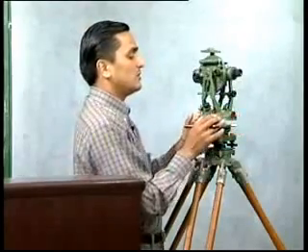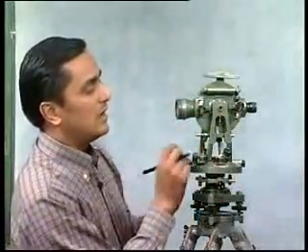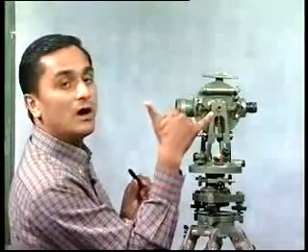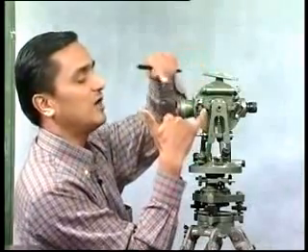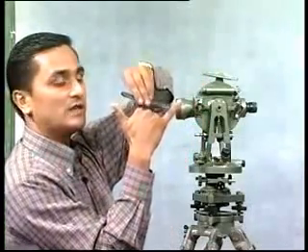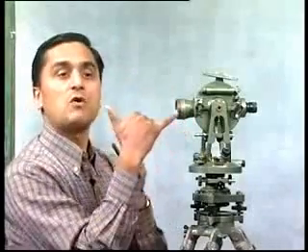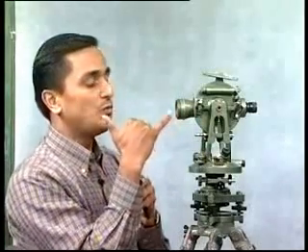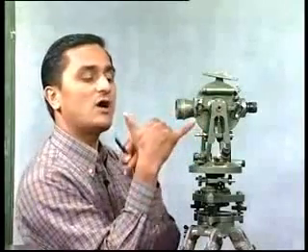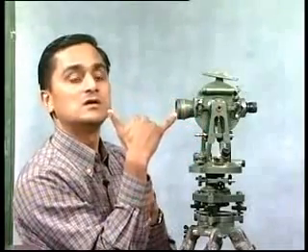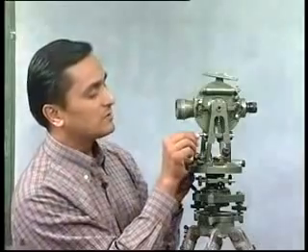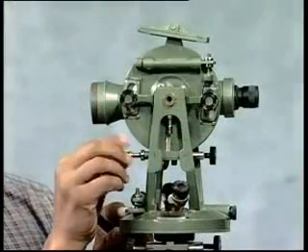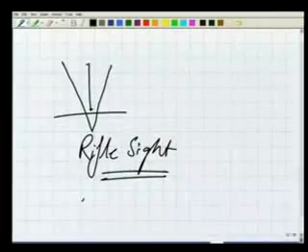Along with this, over here, as we are talking about, we have our index here, vertical index arm, and in this vertical index arm we have the altitude bubble fitted there, and this index arm becomes the reference for vertical angle measurement, and we want to ensure that this index arm is horizontal. Sometimes, after working with the instrument, it might happen that this is not horizontal anymore, it has tilted. How to bring it back? To bring it back, we have one more screw here. We use this screw, and this is called clip screw.